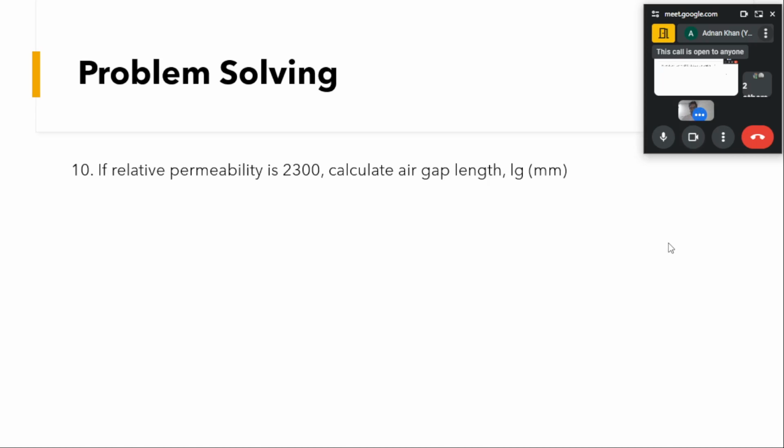And after that, we can calculate the air gap as well. And you can then go for the design check that we had discussed in the slides, and see whatever the requirements are, whether those are met or not. If those are not met, then you have to choose another core which meets these specifications. And that was it for today.